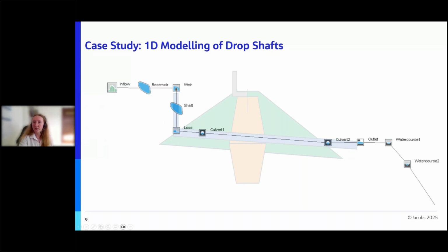At the transition between the vertical drop and the horizontal flow, I'd use an FM general loss unit, picking up velocity from the downstream unit. I'd then represent the horizontal flow through the embankment using a standard culvert schematization as shown.